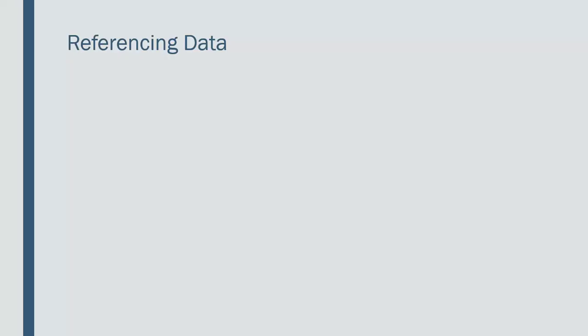So let's take a look at the next step, which is referencing the data. There are two things that we need to cover here, both the external reference, or XREF, and data reference, or data ref, or DREF. I'm going to start with XREF, even though I kind of get a feeling that data ref is more important. They're actually both very important to this process, and doing the XREF first will allow the data to come in behind other things so that it won't be on top and won't obscure things that may be more important.